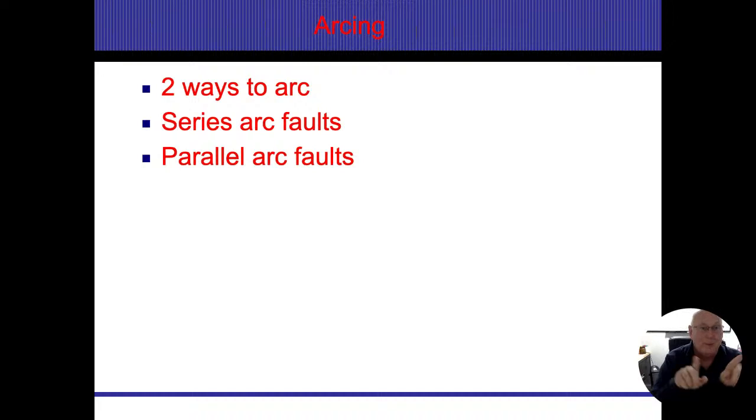are missing. Now those sparks get out of that panel, because those panels are designed to contain any sort of blast or arc or fault that happens inside of them. But if those holes are missing, now it gets out of there. If I've got insulation, wood, anything else, there's a chance that it could start the structure of the house on fire. So simply making sure that all those openings are filled, it's an easy thing to fix, and it's an easy thing to look for.